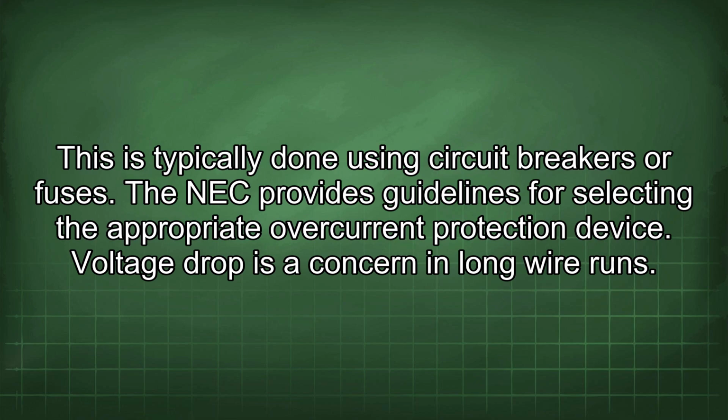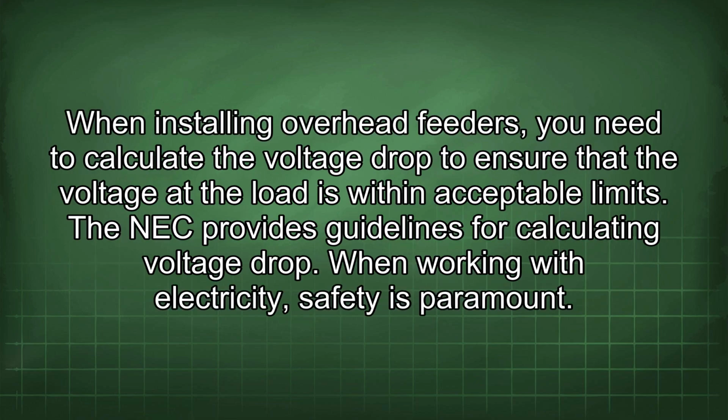Voltage drop is a concern in long wire runs. When installing overhead feeders, you need to calculate the voltage drop to ensure that the voltage at the load is within acceptable limits. The NEC provides guidelines for calculating voltage drop.